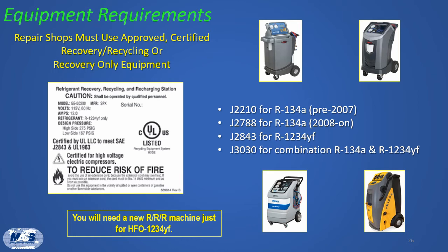R134A recovery machines manufactured prior to 2008 were required to meet SAE standard J2210. Since then, the new standard, J2788, has been required, which offers increased performance, recovers more of the refrigerant from the AC system, and provides greater charging accuracy. R1234YF recovery machines must meet SAE standard J2843, while J3030 provides for a combination R134A and R1234YF machine.